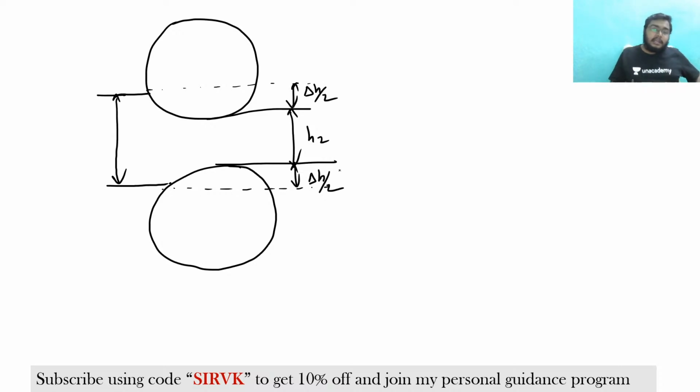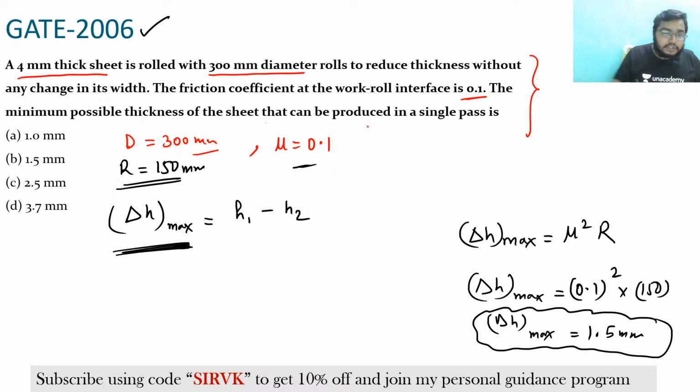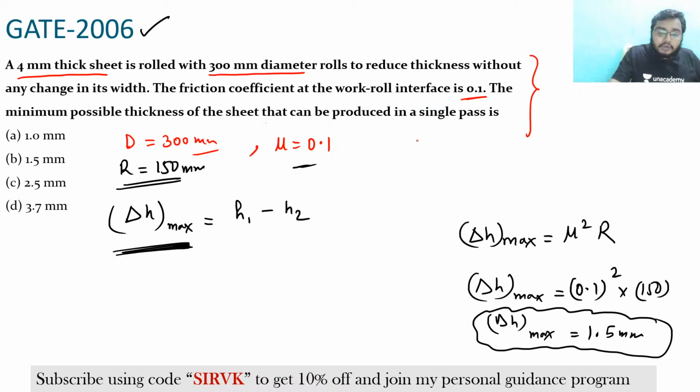Now understand, if this is delta H, the draft would be maximum. If the draft is maximum, so H2 will be what? H2 will be minimum. Yes or no? Now see, in this question, a 4 mm thick sheet is given. So this is H1, 4 mm given. Now you need to find this maximum, so definitely H2 will be minimum. So how can you find it? This H2 will actually be minimum.